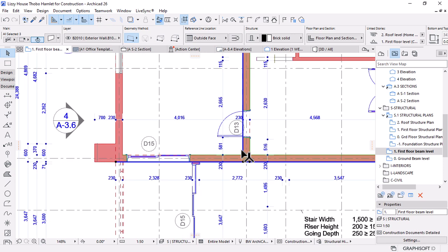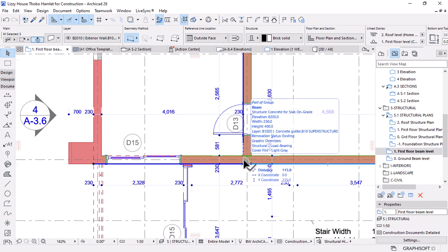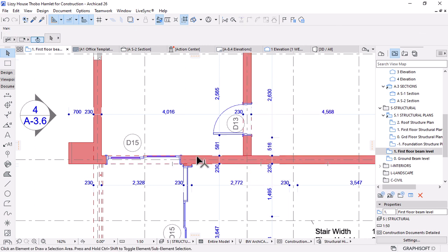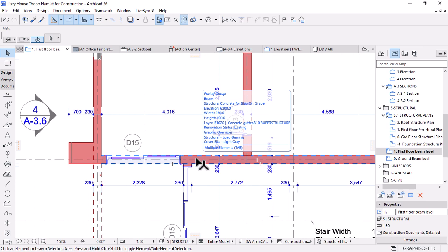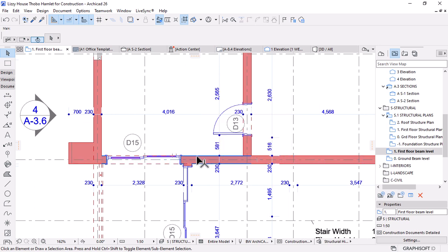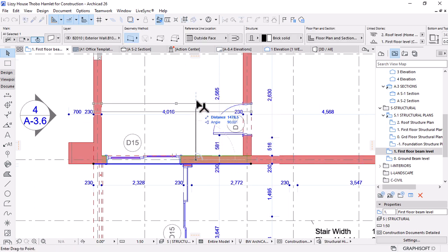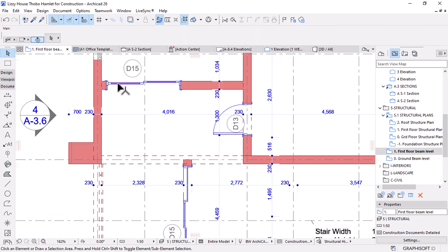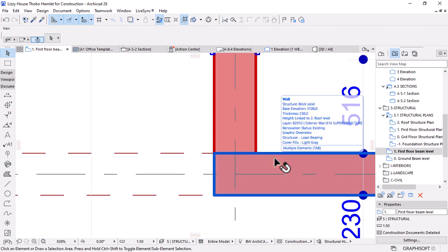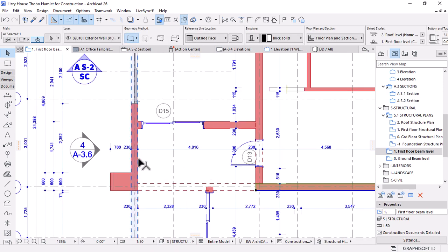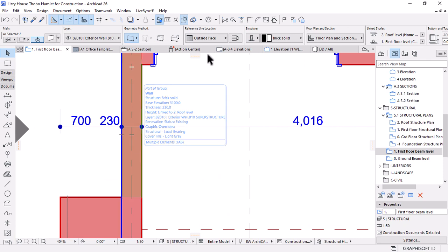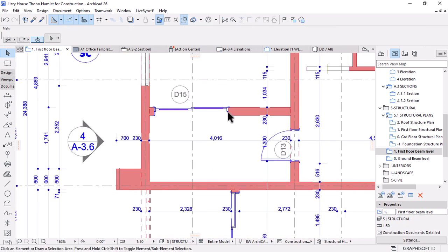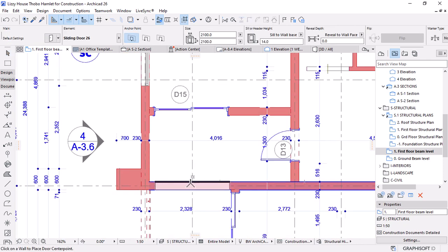Select all the walls, but that's the problem when you trim your walls like that. To permanently solve this issue, I'm going to get rid of this wall. Let me just move it here, because I want to copy the parameter of the door. Then select this door, this wall, and I'll fillet it with this one. Join them here, pick the door, and then place.